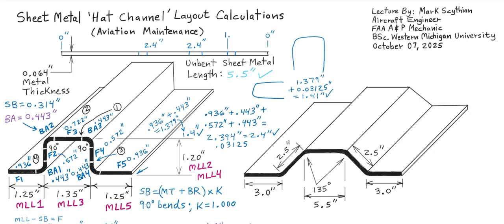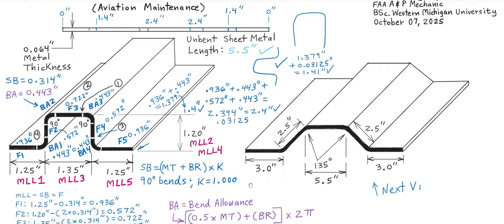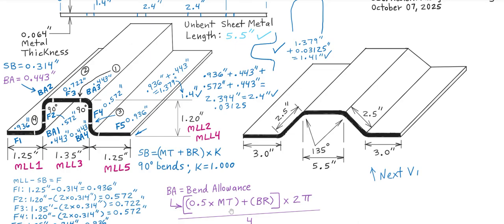So that's where your third bend will be, right here. So you have bent this downward, these two, you have a bracket, then you have to bend this one upward. And then you do the same thing on the other side. So now you've bent the hat channel outward and you're finished. So this one here is a 135 degree hat channel. Just to keep things simple and on point, I'm going to make another video and it will cover this one.